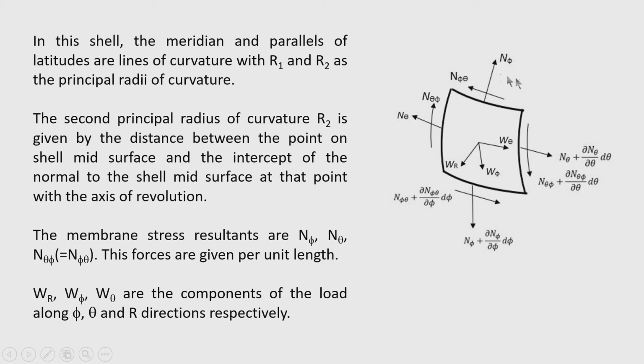So, you have seen that here on the element, the forces acting along the edges in tangential direction, that is the shear force, and in the normal direction, that is the direct membrane force n theta and n phi. So, we have to form the equilibrium conditions of this element to analyze the shell, and then we get a differential equation.